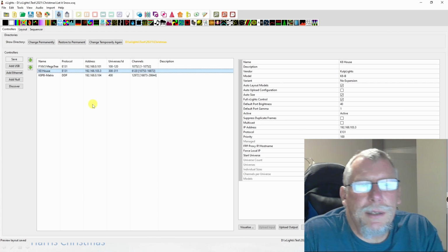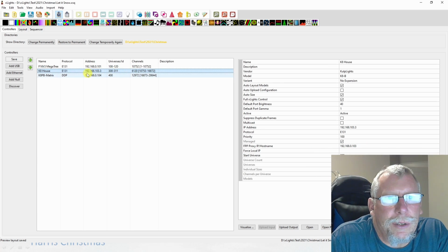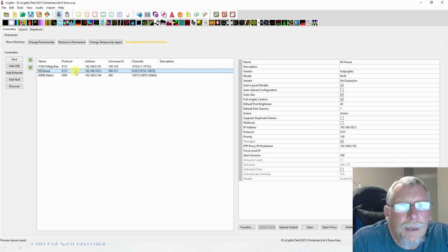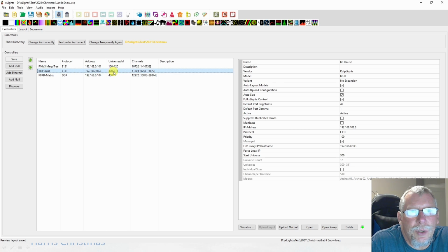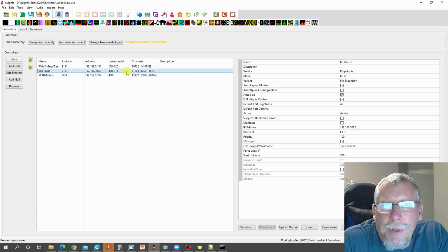So you got to look at xLights, and you got to look at the channel configuration. So the one that we're going to configure is this one here. So it has 12 universes. Remember the 0, you got to count that one, and it starts at universe 300. The start channel is 10753, and we are not doing multicast. It's recommended to use unicast unless it doesn't work properly. And channels per universe is 510. So you have to remember what that is.